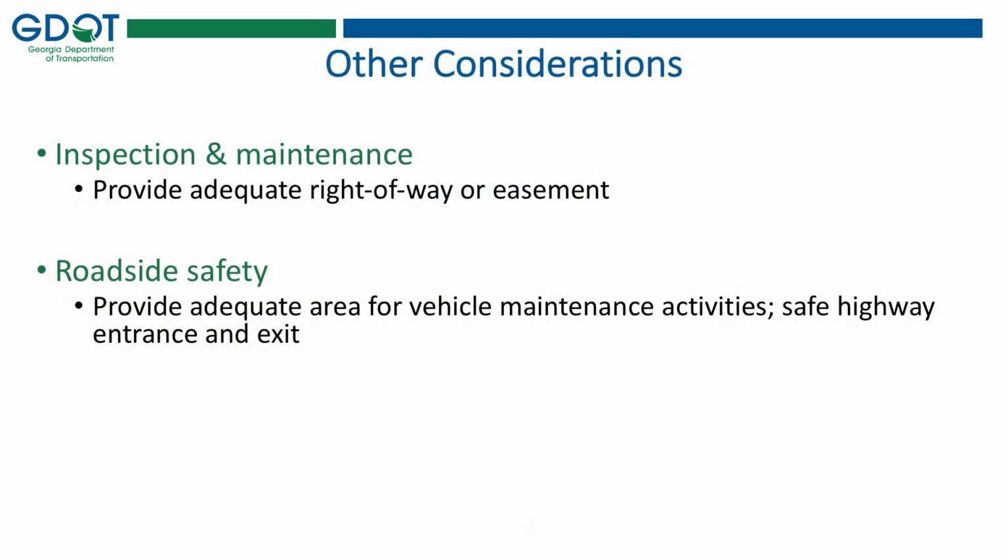Filter strips, when installed as an MS4 BMP, become GDOT assets and require ongoing inspection and maintenance. So during the design process, the designer should ensure that adequate area is provided that allows for safe roadway entrance and exit for vehicles performing BMP maintenance activities and inspections.